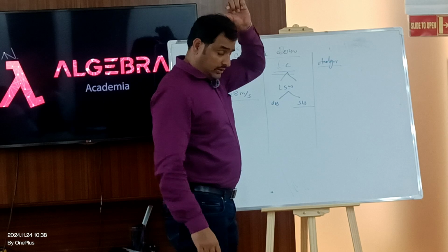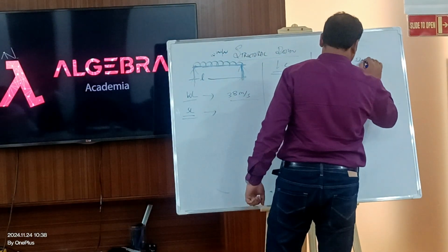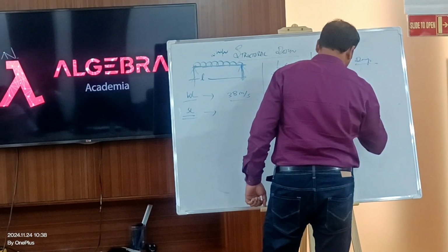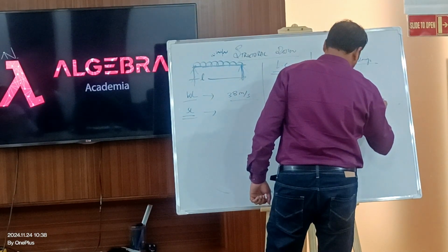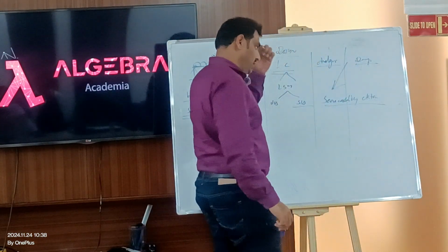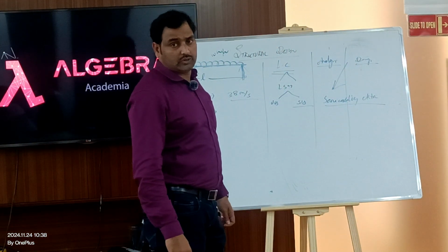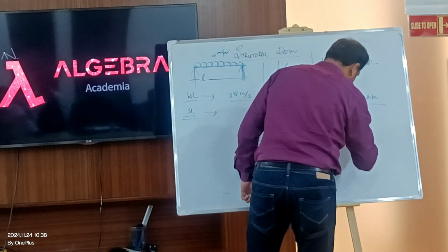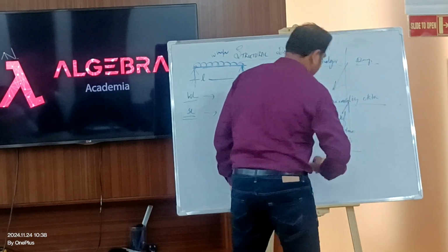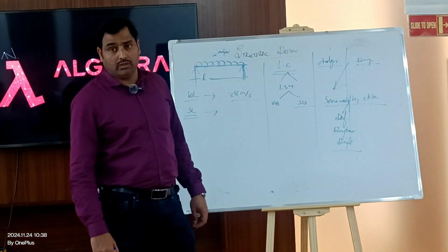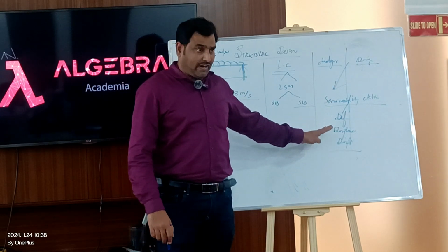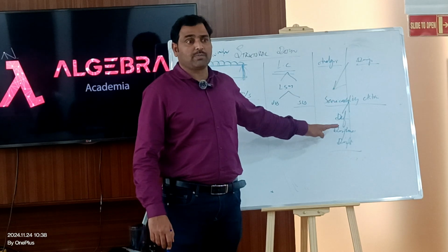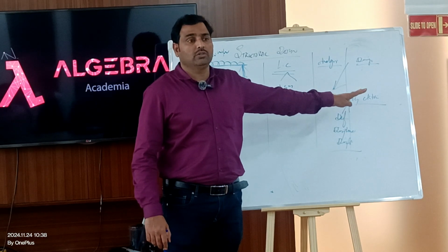Another one is analysis, right? The next one is design. So before design, we do have a check, which is called the serviceability criteria, the serviceability check. The serviceability check will be defined by deflection, by displacement, by drift. In fact, it is all deflection only. This we have already seen, right? Deflection is related to gravity load, displacement related to wind, drift related to seismic.